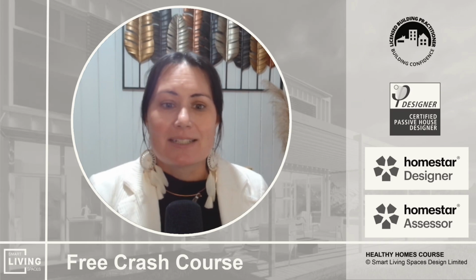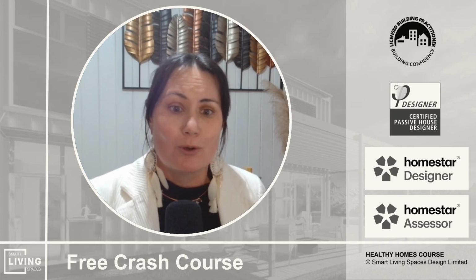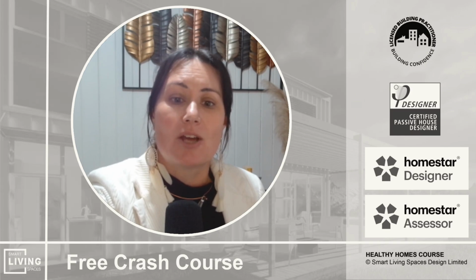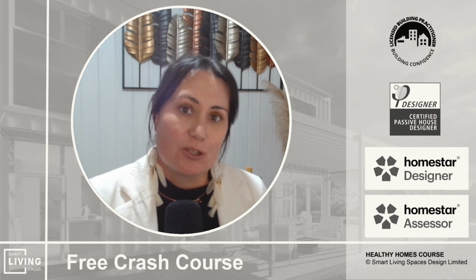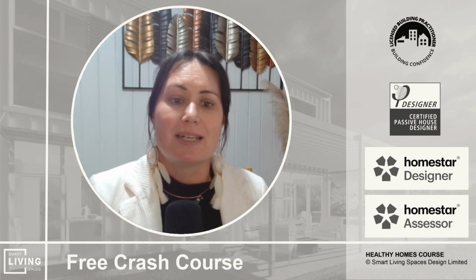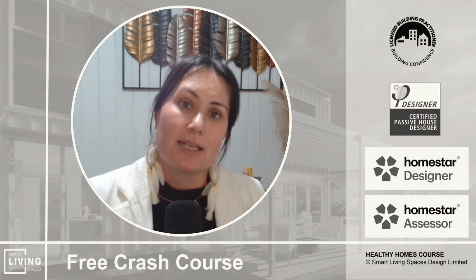Now, before we get started, I just want to remind you that the house is a system. So any upgrades or changes that you do will impact on other areas of your home's performance. Sometimes these can work against each other, so it's important to find the right balance. For example, if we have an airtight home, it's really good at reducing heat loss, but we have ventilation and moisture issues that need to be addressed. And a slightly air leaky home is not great for heat loss, and there's the issue of moisture getting trapped in the structure, causing rot issues that you might not be aware of. So we need to consider these things together and not simply in isolation.